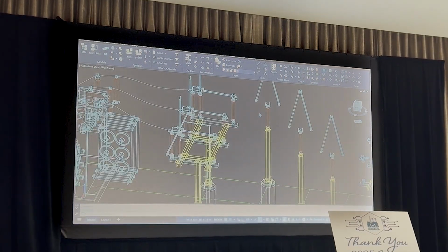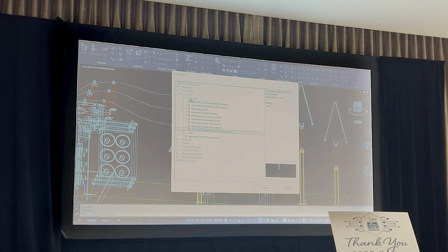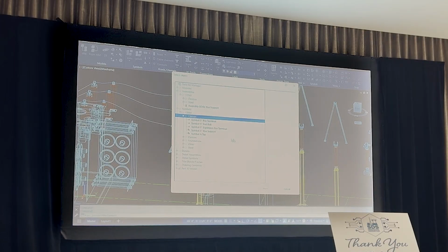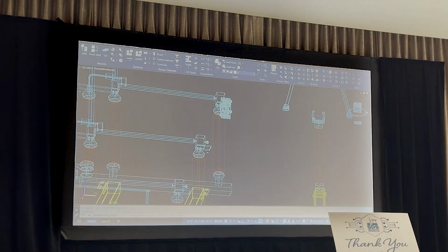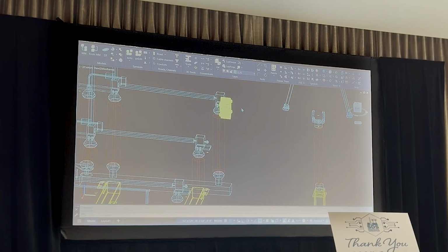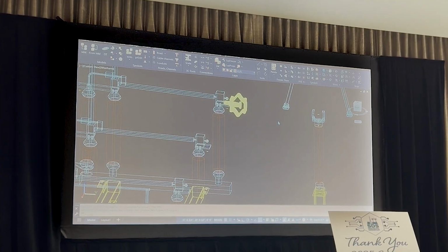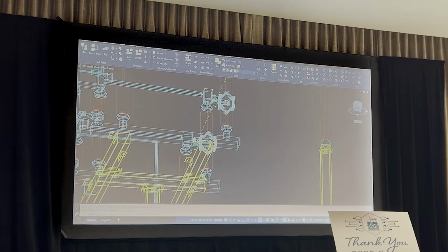Then we have bus. So bus, I said I do want to put fittings. So we'll go ahead and place some fittings on that one. So I'll go here to my symbols, clamps. This one we're going to put in expansion terminal. I'm going to snap it to that point. Again, I don't really want this one to be facing that way, right? So I can hold shift and I can rotate those around. Then I could copy those across to different locations using those node snaps again.